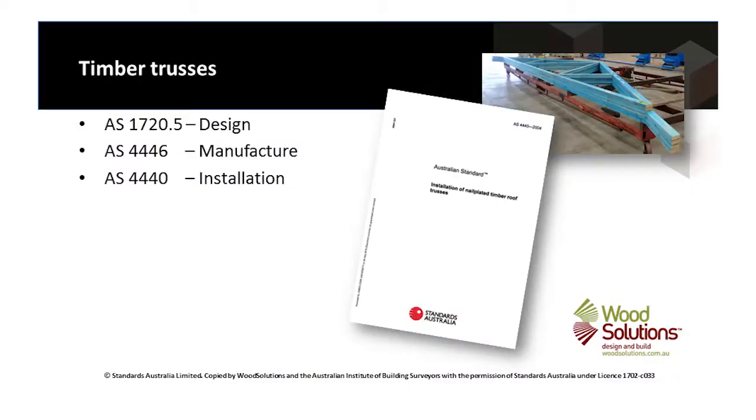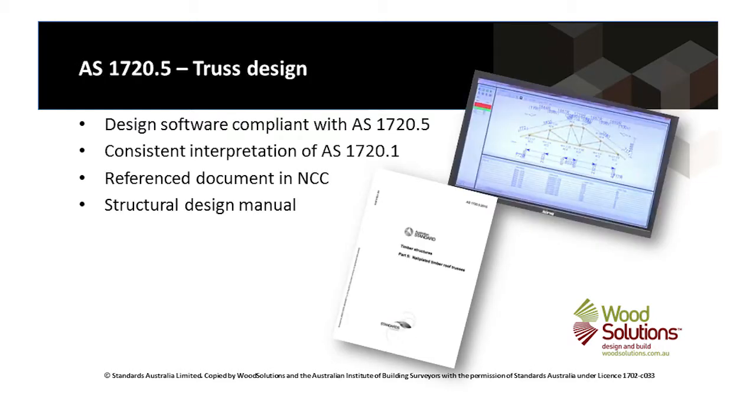Timber trusses, there are 3 standards that are important in timber truss work: a design standard, a manufacture standard, and an installation standard. And each of these will become part of the documentation for timber trusses. The timber truss design standard is relatively recent, and it contains all of the design criteria that are used for trusses. These design criteria are acceptable and compatible with AS 1720 Part 1, the primary timber design standard, but they give a uniform footing across the entire truss industry.